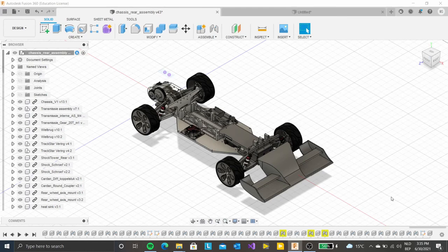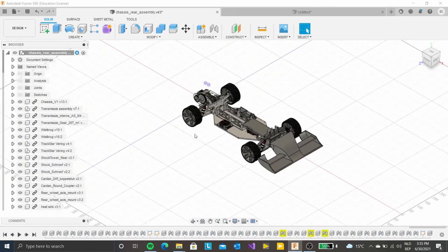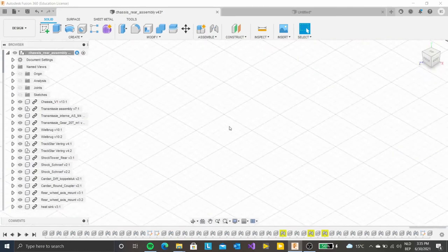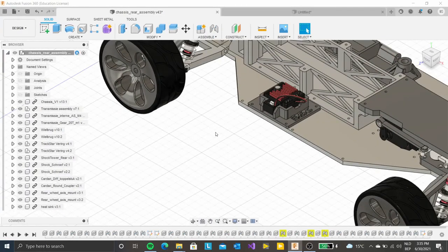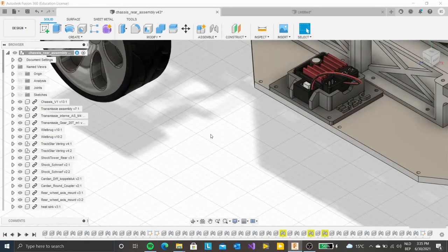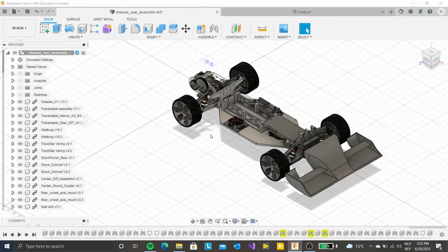So, what do we have next? Next, we do have the canvas. The canvas is the workplane that you can see in the background. As you can see, it has a grid and it has the Z and X axis labeled on it. You can see the red and the blue axis. When zooming in or zooming out, you can see that the grid size changes. So for instance, it will go from 5 millimeters to 1 millimeter to maybe 10 millimeters. In some cases this is useful if it automatically adapts, as it does now, but in some other cases you might prefer having a fixed grid.